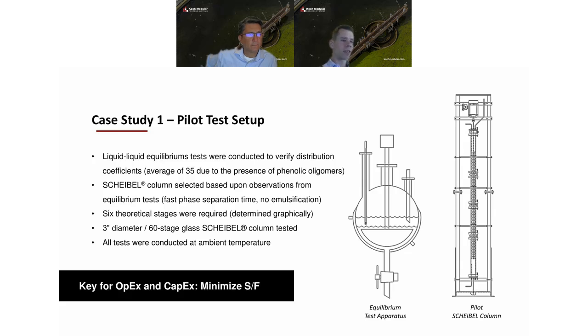Mix them together at high speed for 2 to 5 minutes, allow the phases to separate, take samples of each decanted phase, and analyze them to determine a distribution coefficient. So if you had a process you were developing and there are a few solvents that looked attractive, we'd run a series of these, say 1 to 2 shakes or mixed-and-decants per solvent and per feed, to identify the solvent that's most effective for that process.